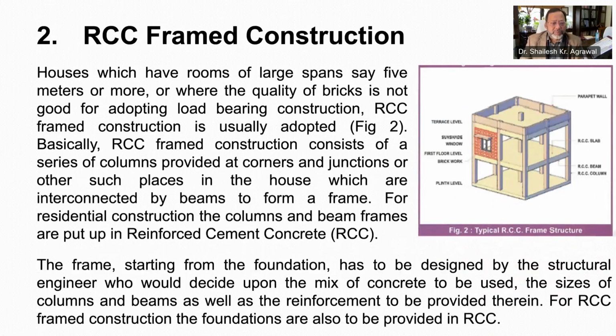Now let's move to the next category, which is RCC frame construction, shown here in this figure of this slide. This RCC frame construction consists of a series of vertical members called columns provided at corners, junctions and other places in the house, which are interconnected by horizontal members called beams to form a frame or skeleton of your superstructure.